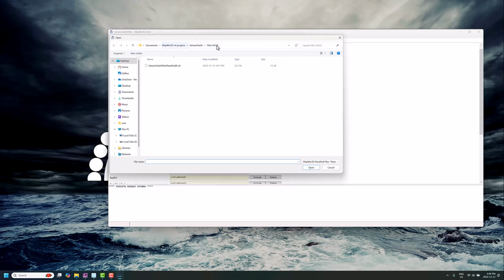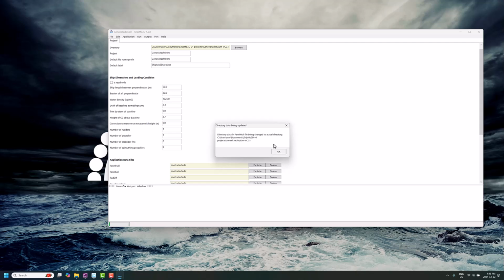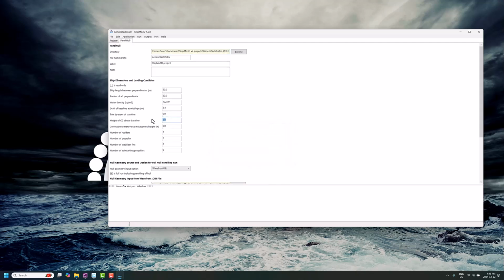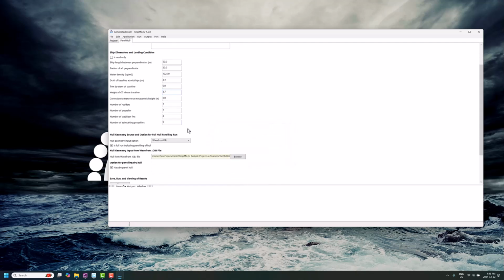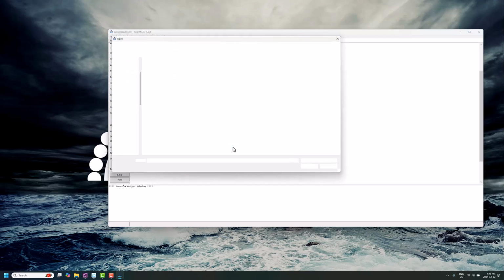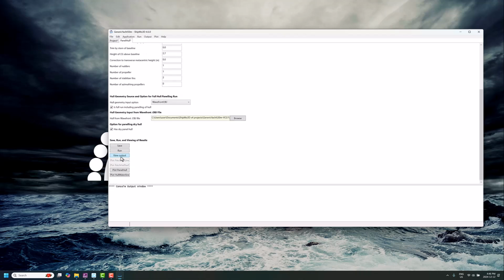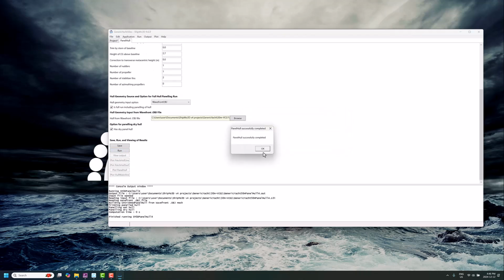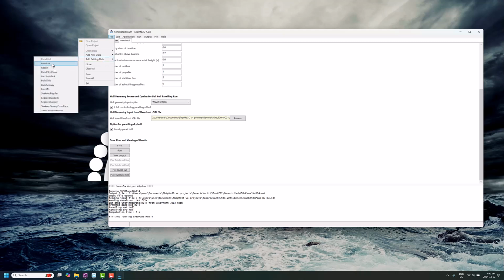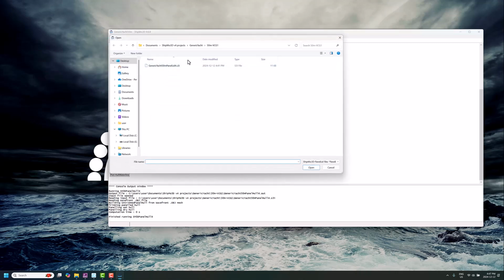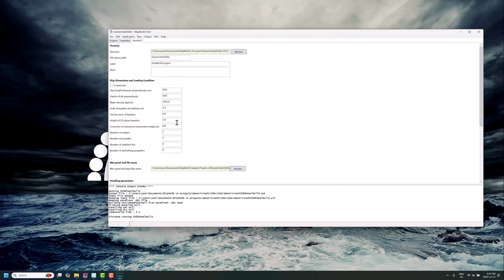Now you want to be really sure you're looking at that VCG1 and opening up the input files for that. And you'll need to change this value. Again, be really careful with the file paths. Look at the deck half of the hull. We'll run that. Go to the panel lid, VCG1. Height of the CG above baseline, 2.7.